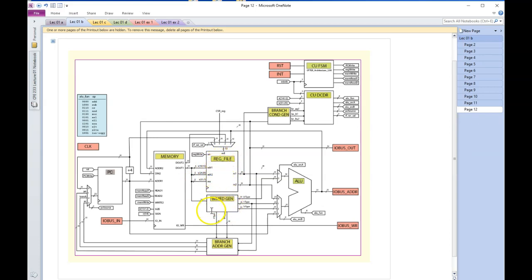This is a combinatorial circuit. This is a combinatorial circuit. You can see a bunch of muxes plopped around here. You know what muxes are. This is the ALU, arithmetic logic unit, which is another combinatorial circuit, no big deal. Here's the branch condition generator, a combinatorial circuit, which is effectively just a comparator. Here are your control units. The control unit is actually broken up into two modules, which I'm not agreeing with quite 100%, but we're going to go with that.